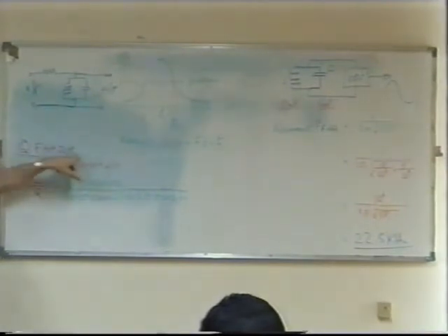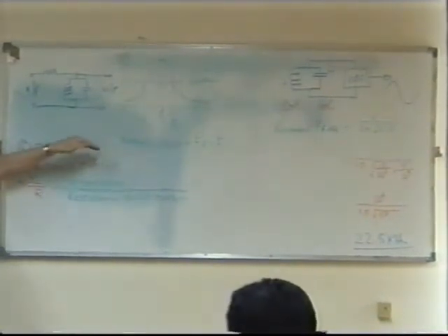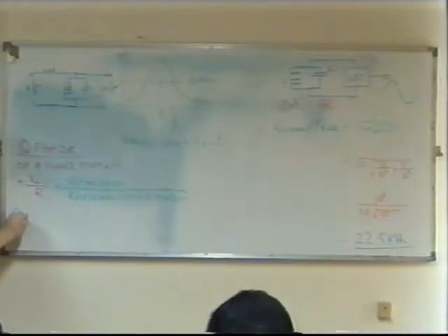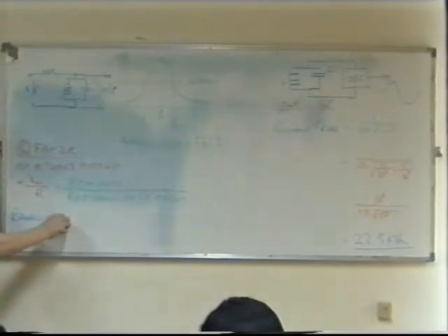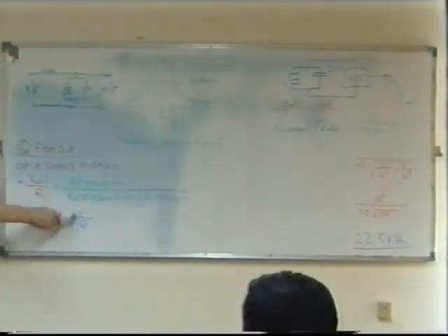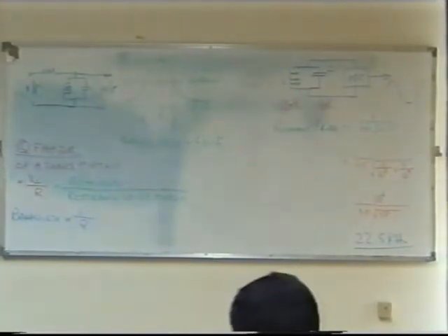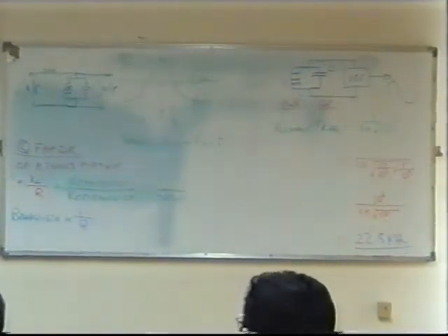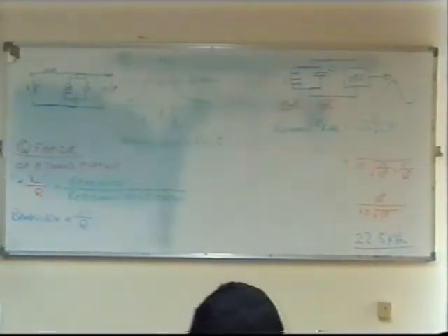I didn't mention Q factor yesterday. I should have mentioned that, but I want to make sure you understand that before we continue. Q factor, that's what it is. And the bandwidth of our filter is proportional to 1 over Q. I'm not going to give you the full formula, but I'll just give you this simple 1 over Q. Inversely proportional to the Q factor. The bigger the Q factor, the narrower the bandwidth. Yes, the narrower is going to be the bandwidth.